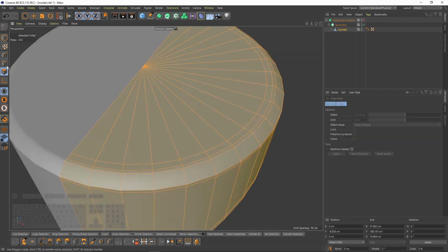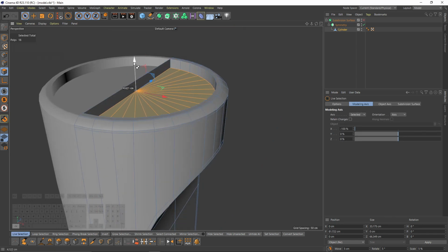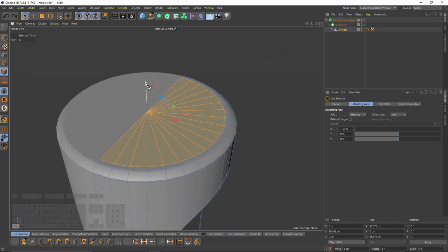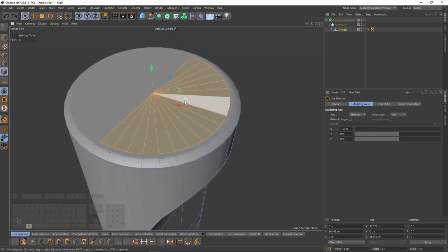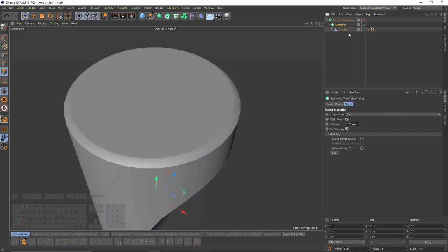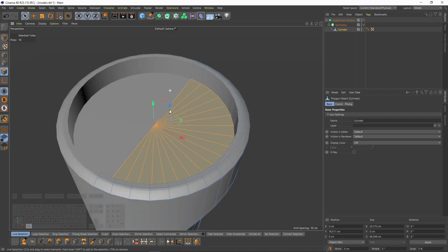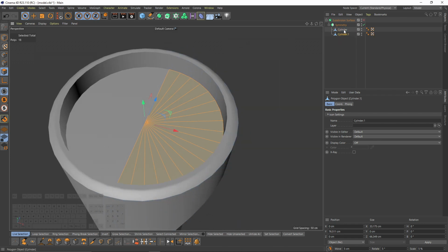Okay, that's enough. Now I will select these polygons, press Ctrl and move on the y-axis. But before that, when I do that, as you can see, it created polygons. You can actually get rid of that. Go to symmetry and enable these options. This is gonna delete these center polygons automatically, like that. Now I will right click, split, then go to the first object and delete.